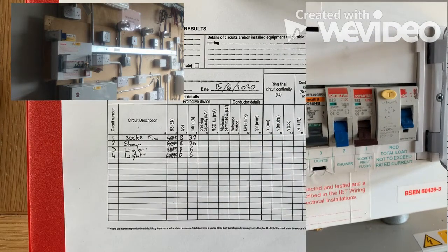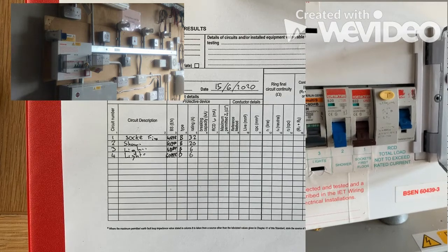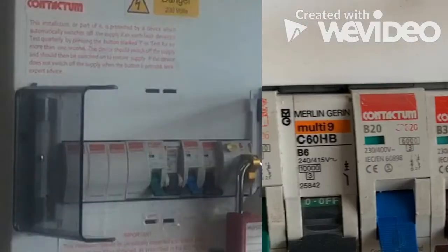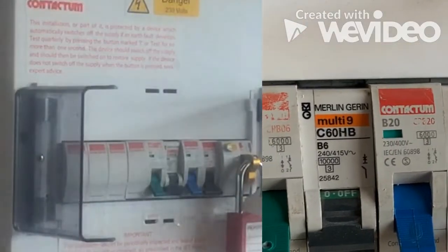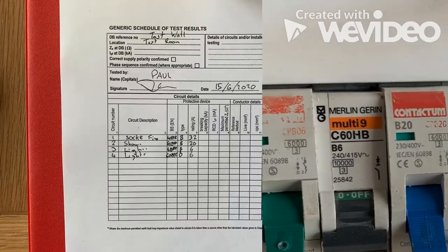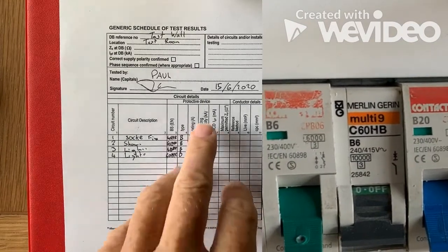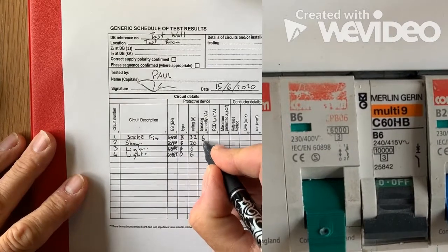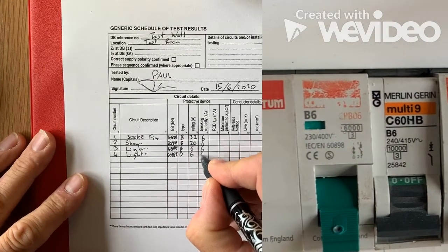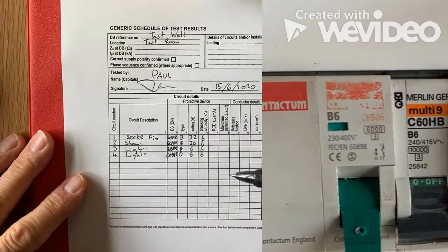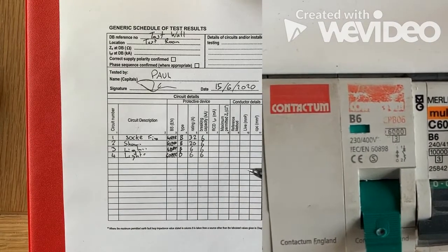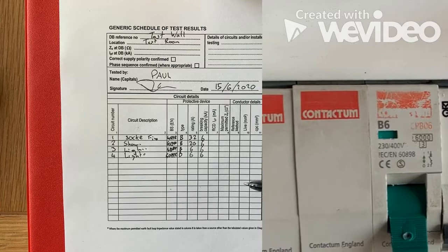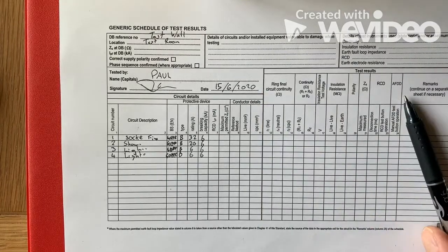And then we would look at the breaking capacity. And we would look here in this little box, and I'll show you on something else if I can add that in there, but we can see that we've actually got 6,000. So our breaking capacity is 6,000. Because it's in kA here, we just need to put 6. So our breaking capacity for all our breakers is 6. And then what we would do is have our maximum permitted Zs and our reference method. And we'll have a look at those in a second, and we'll look at the reference method and we'll look at the cables.